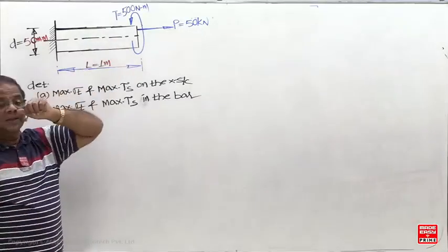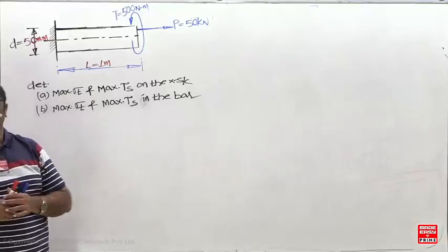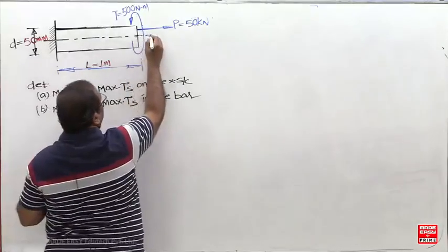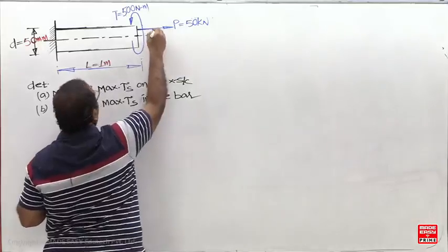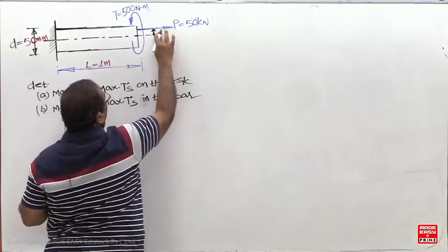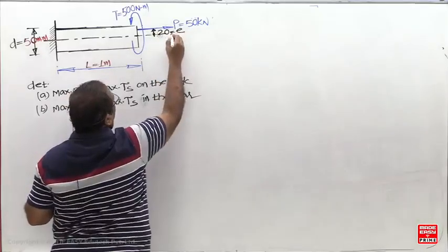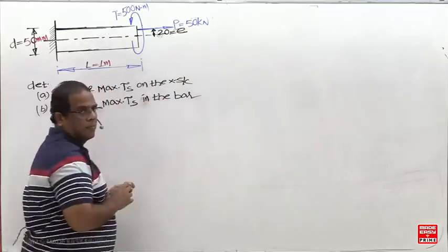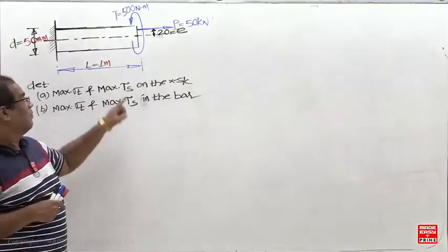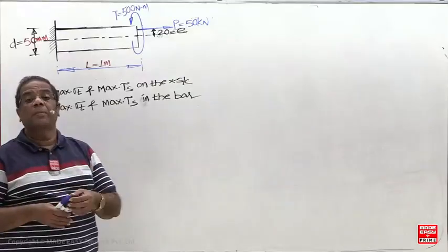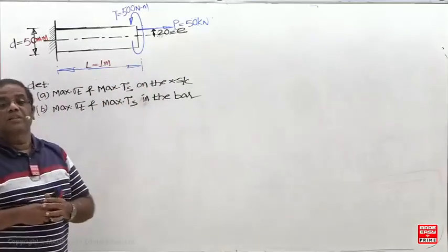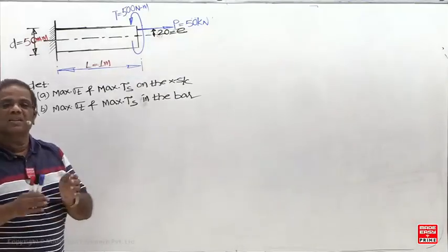You have to see the axial stress and bending stress, then see where the resultant normal stress is maximum, where the bending stress is tensile and where it is compressive. For an eccentric axial tensile load, first you put the axial load and bending moment, then see the sagging and hogging, in the vertical plane or horizontal plane. Then you see where the bending stress is tensile and where it is compressive. That is the actual method.